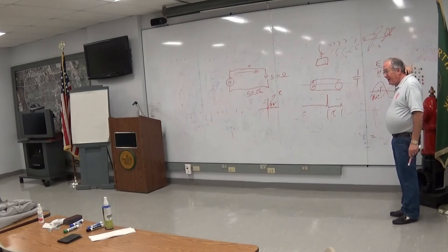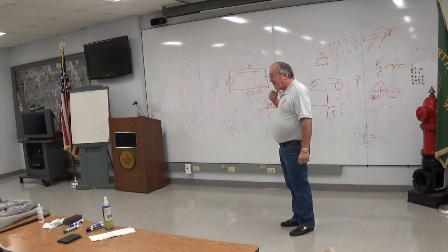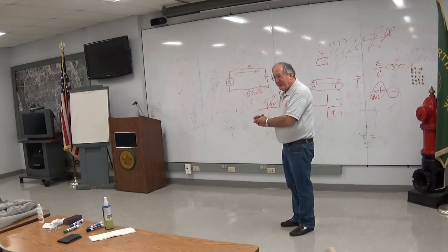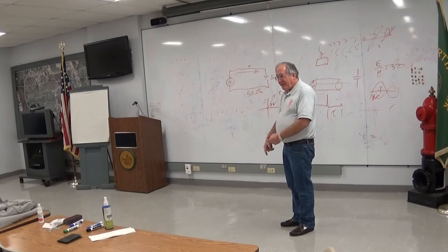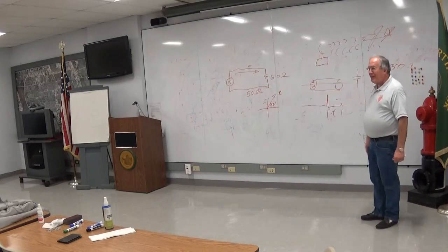You're trying to get the discontinuities to not be there. If you have a sloppy connection, like a bad connector on the coax cable, you're going to get reflection. If you have that ring around this piece of twin line, you got the reflection of the discontinuity in the transmission line, which is why we got away from twin line.